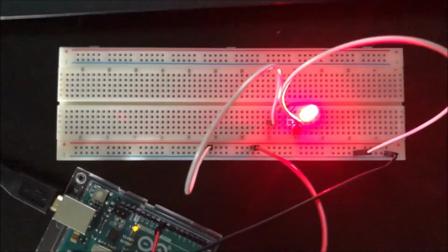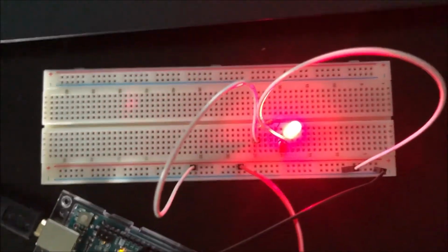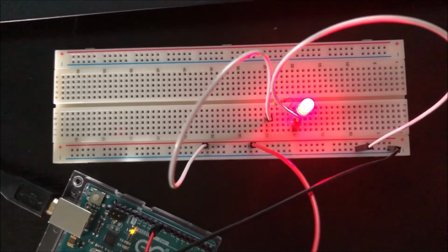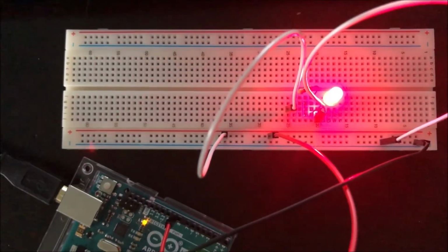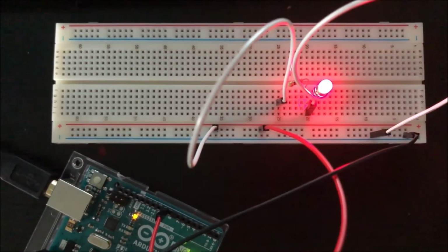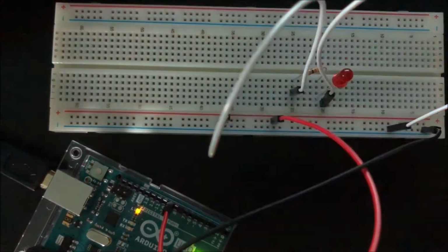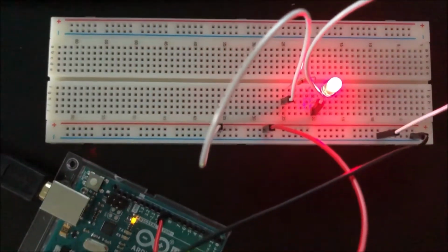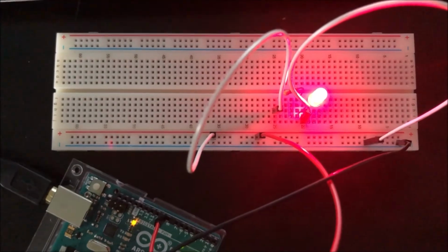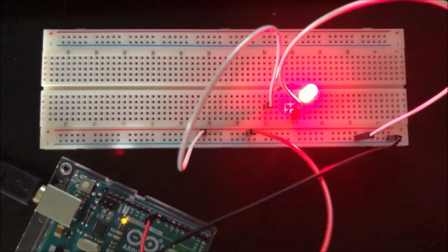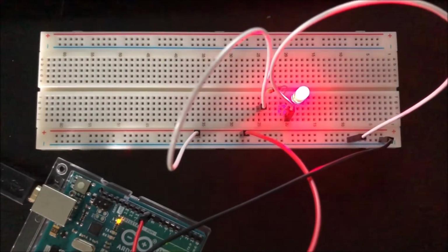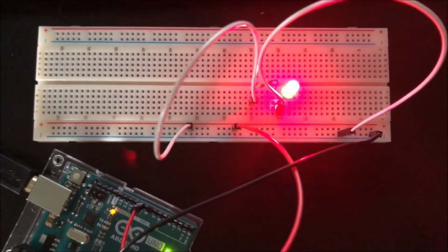Now the two delays that I have in the for loops are always functions that will sum to 2 milliseconds. This is so that the code maintains the 2 millisecond pulse width modulation period that we saw in the analogWrite period. So for example, my delays are set to one value minus 10 of itself, and the other value is 2000 minus the previous one. This way, they always coincide to sum to 2000 at every point in time, and we can simulate pulse width modulation using the digitalWrite feature.